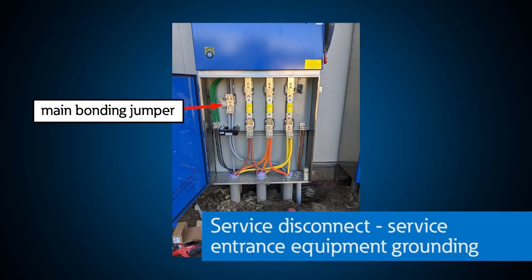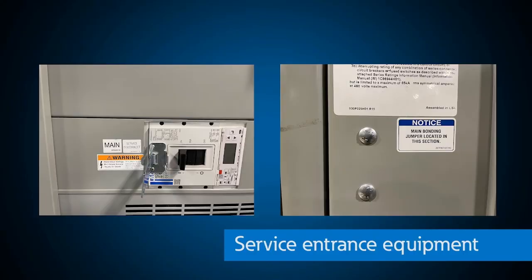For larger systems like the pad-mounted transformer or the switchgear, if the utility owns the transformer, we would see the neutral to ground bonding jumper installed inside our switchboard or switchgear, and we would bring the grounding electrode conductor into that service equipment. That is why it is clearly marked as service entrance equipment or suitable for use as service entrance equipment, because it has the capability to bond the neutral to conductors inside that equipment.